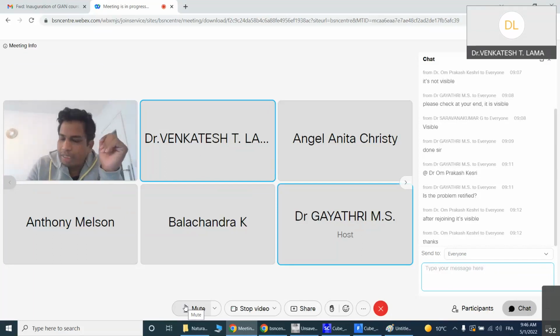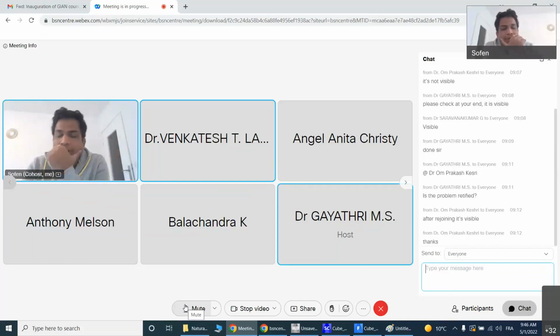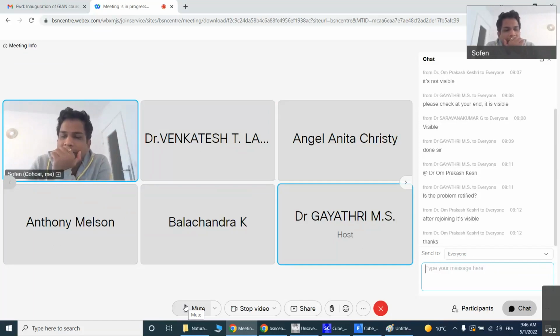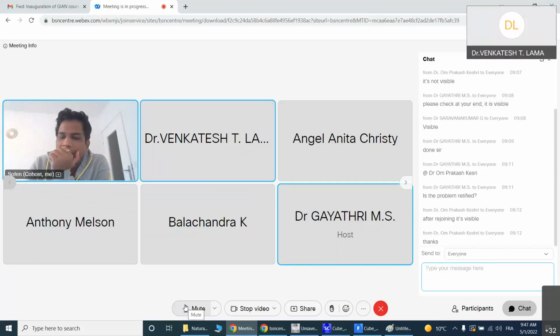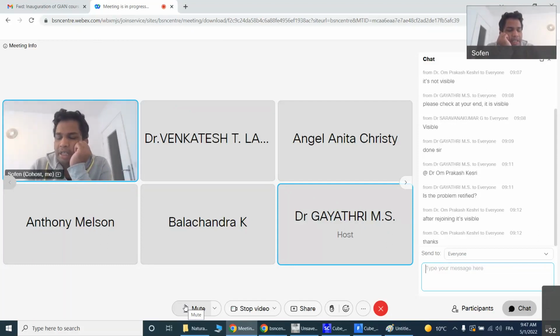So Venkatesh, your question is not clear to me. What exactly is your question? Now the models which we have selected, Boussinesq, we selected for natural convection. If the same problem is solved for forced convection, what are the changes in the overall settings of the problem? Okay, what exactly does forced convection mean? There is some external source for the movement, right? In natural convection, the buoyancy drives the flow. If it is forced convection, there should be some external movement that drives the flow.